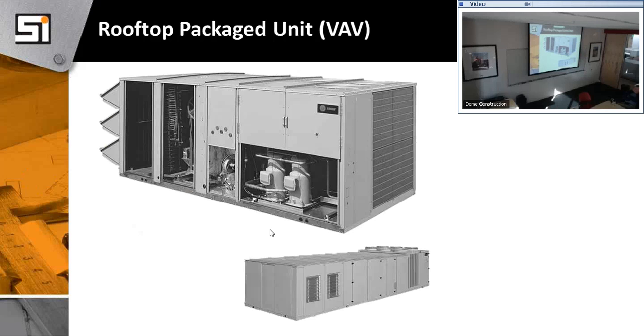Now we're getting larger units. These are the big ones you see on the roof. It's a package unit, so self-contained, all the refrigerant, the control, everything's there. I have ducting dropping off the bottom, or I think a lot of you probably see a lot of side ducts, because of acoustics. With these big units, you really can't drop straight down and serve the space, because of the acoustics of the unit. So we try to go to horizontal duct on the roof, where we get low frequency breakout. If you insulate it, you get some high frequency attenuation. And then we can select where we drop, so it's not over any sensitive areas.